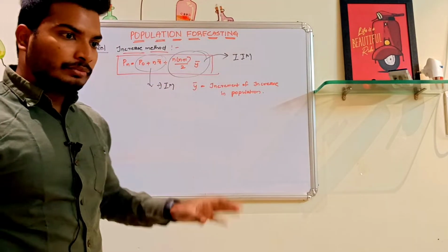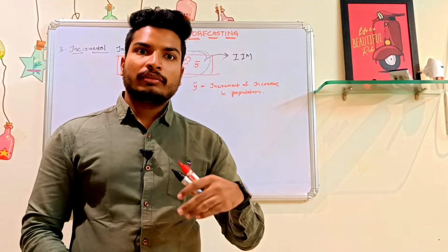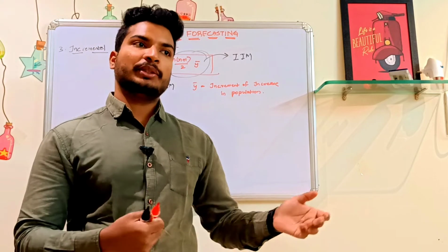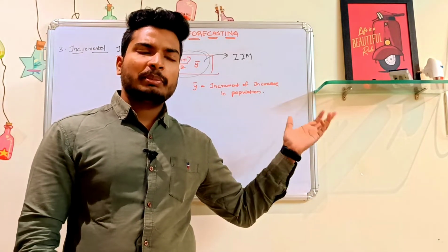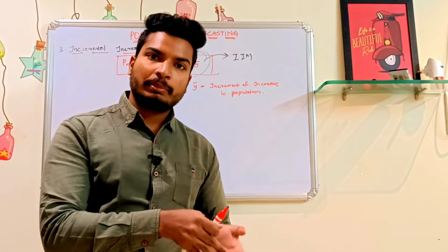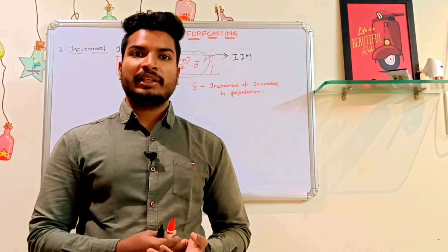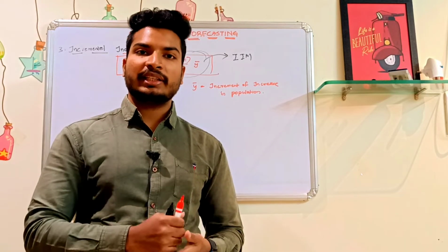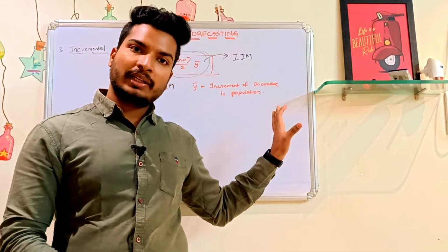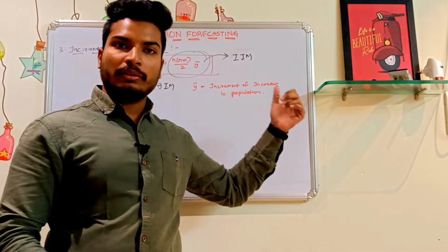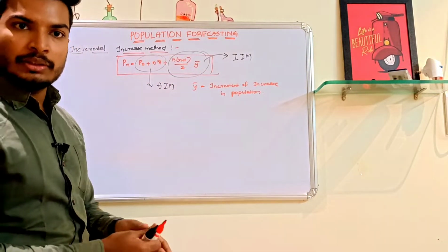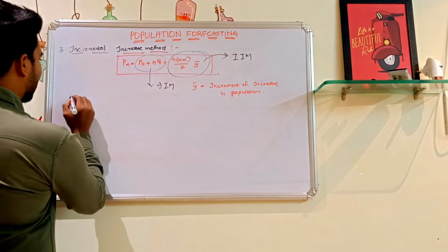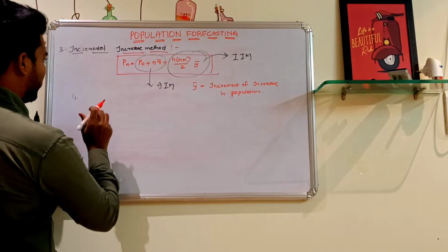By this method, there are different types of cities where incremental increase method can be used, because there may be different kinds of situations in that particular decade where the population has decreased, and also later on due to development the population is again increasing. So there we'll be using this formula. We'll also be solving the problems on all the types, so you just don't need to worry. So finally the fourth and last method is the decreasing growth rate method.